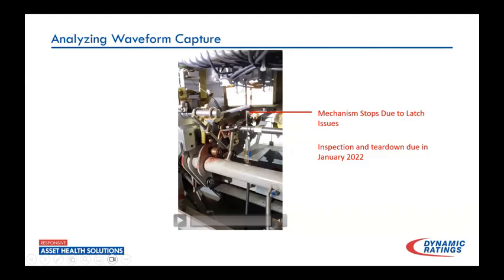So just to give everyone some reference here, what you're looking at, this is a switchgear type breaker. It's racked out. And we're going to see the plunger is going to come down from right here. So relay's going to initiate, coil's going to energize. We're going to see this plunger start to move. However, if you look here, we have a sort of a flap that's attached to a spring. So not actually hitting an actual latch. So that's why we're not seeing the latch in the signature, but it is going to initiate the latching mechanism.